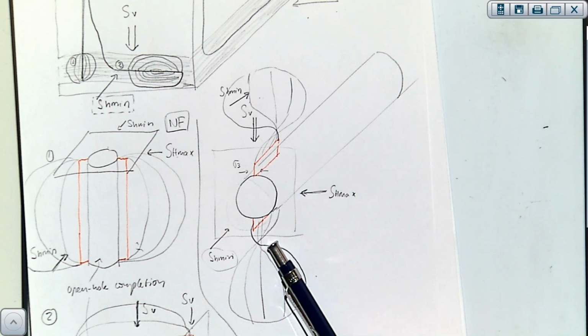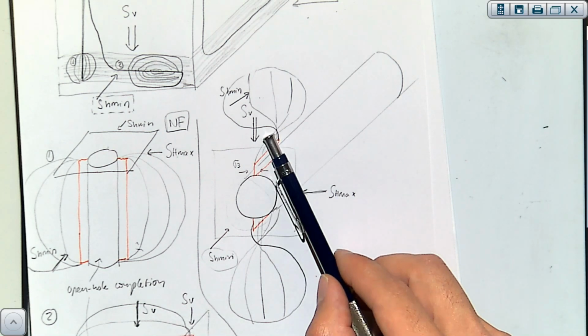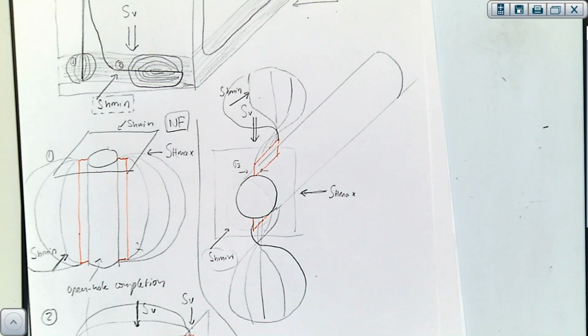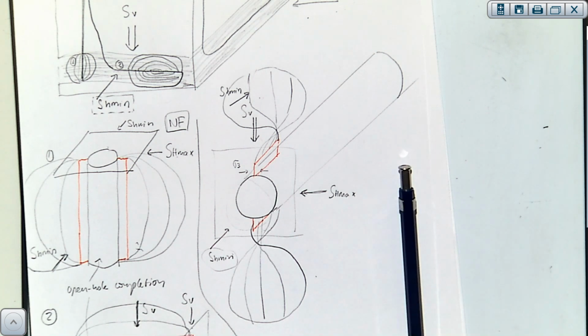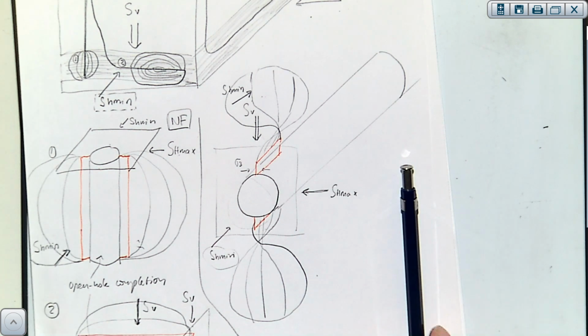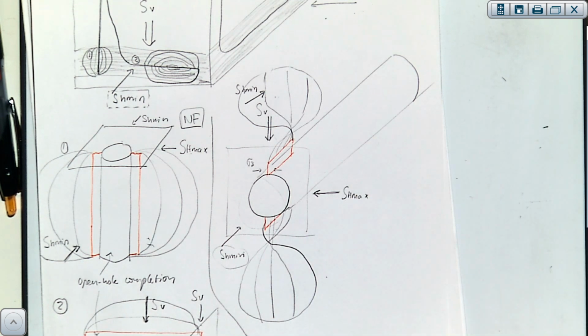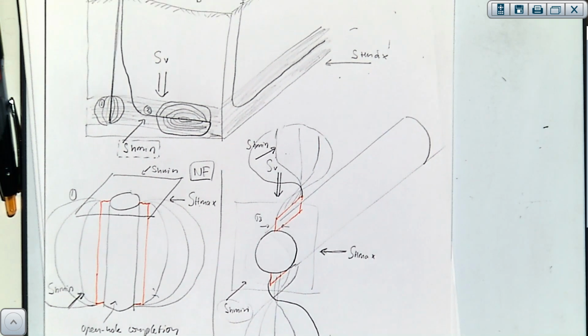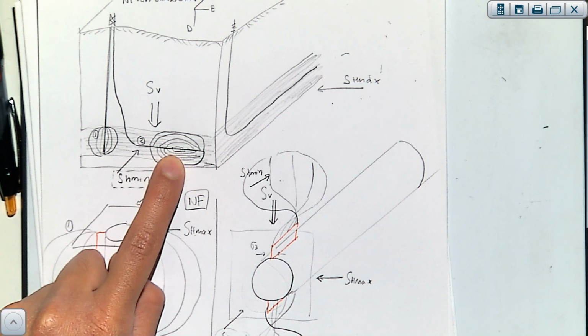And actually, in order for the fracture to grow and to go through these points of high fracture complexity, the fracturing pressure that you're going to need is also going to be a lot higher than if you didn't have that. So what do you do in order to avoid this kind of tortuosity near the wellbore? Well, actually, but look, if you change direction, you're going to end up with something like that.